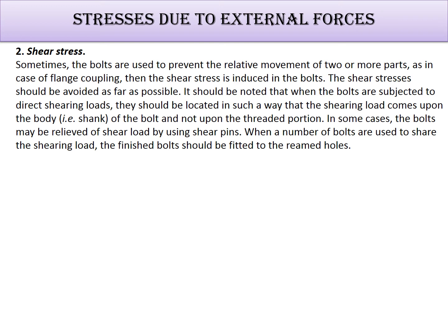Now the shear stress which is induced in the bolt. Sometimes the bolts are used to prevent the relative movement of two or more parts. So in case of a flange coupling, the shear stress is induced in the bolt. So the shear stress should be avoided as far as possible. Just remember this part, that we need to avoid it.